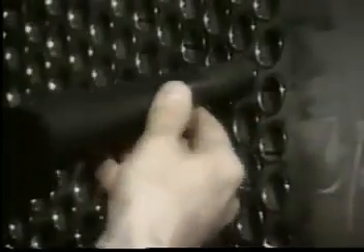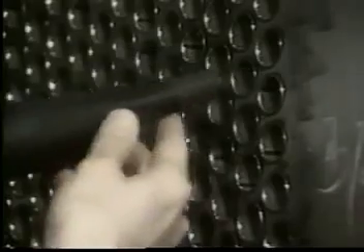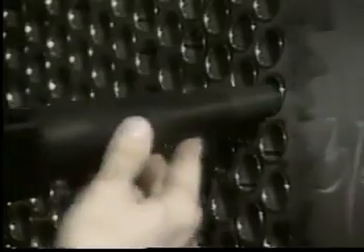Once the general area of the leak has been found, insert the rubber focusing probe and compare the sounds to neighboring tubes. A leaking tube will produce a louder sound. Test both ends of the heat exchanger.